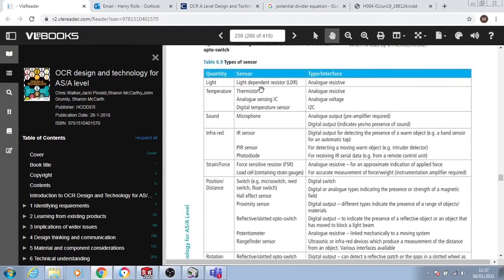And the ones that change the resistance are going to use a potential divider to be able to control an input voltage. You might have a sensor that's got a minuscule voltage just generated, something like a thermocouple, which is another heat sensor. Just when it gets really, really hot, you get tiny, tiny voltages out of a twisted wire of different types of metals. And in that case, you might want to use an amplifier or 2 amplifiers or 2 transistors in series just to amplify that circuit. But we'll cover that in a different video.